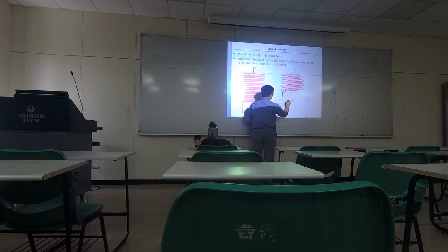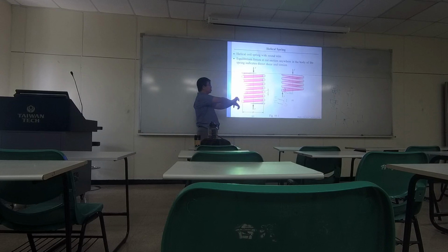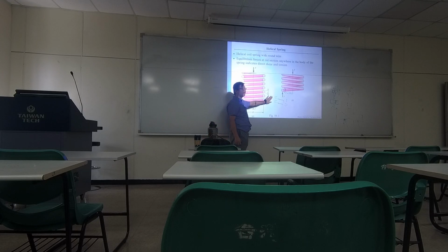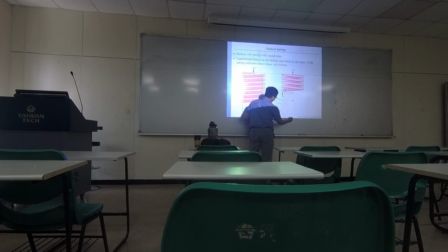So this is coming, the direction is up and down, and the torsion basically is following the direction of the squeezing. So every time you compress a spring or pull the spring, everywhere inside this helical wire is carrying shearing forces, shearing stresses in different ways. So you will need to compute the total shearing stress. So it's like you can sum them up, okay?